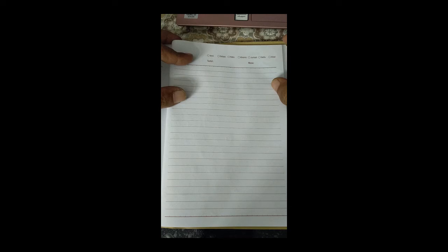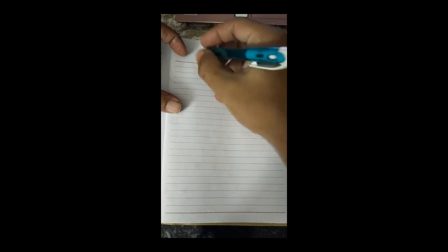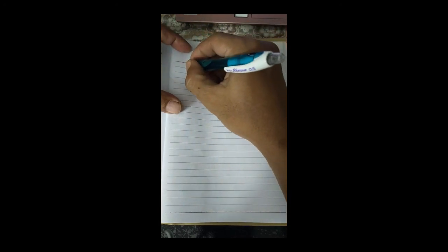The mass flow rate of the air is 0.02 kg per second and a heat loss of 16 kilojoule per kg occurs during the process. Assuming the change in kinetic and potential energy are negligible, determine the necessary power input to the compressor and take specific heat at room temperature. So, 3.16.